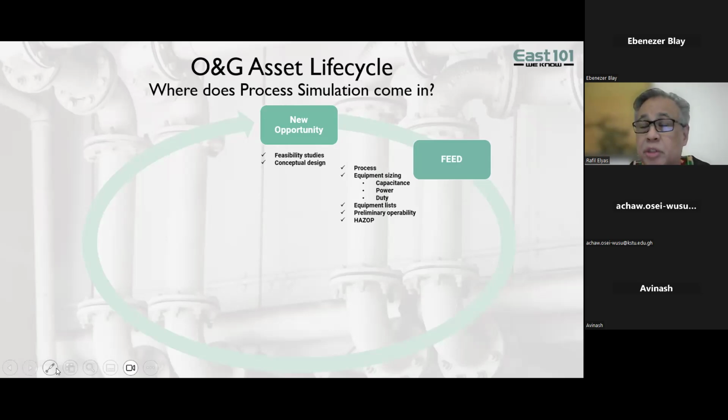So HAZOP is going to be pretty interesting because when you're looking at HAZOP or hazards identification, you might be looking at phenomena like a sudden valve closure. If I have a valve closure, something's going to happen. I might get an increase in pressure. Now we're starting to look at the time domain and system responses. So maybe you might start looking at some of the system responses for this kind of analysis, and you might turn to some kind of a dynamic model, yeah, or transient type model. And that could be anything ranging from MATLAB and Simulink all the way up to full-blown HYSYS.